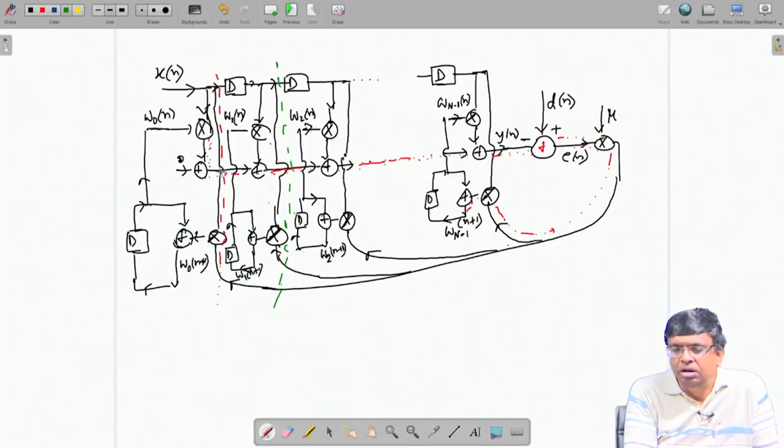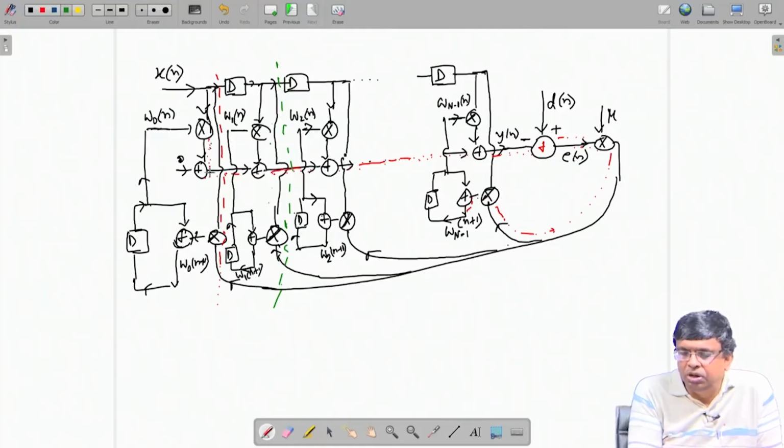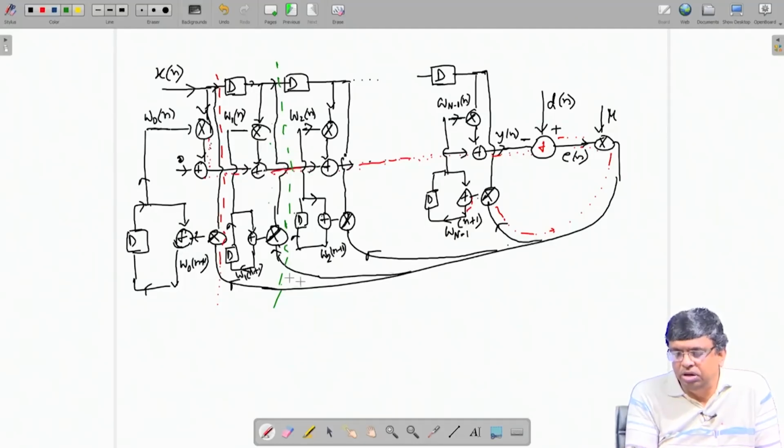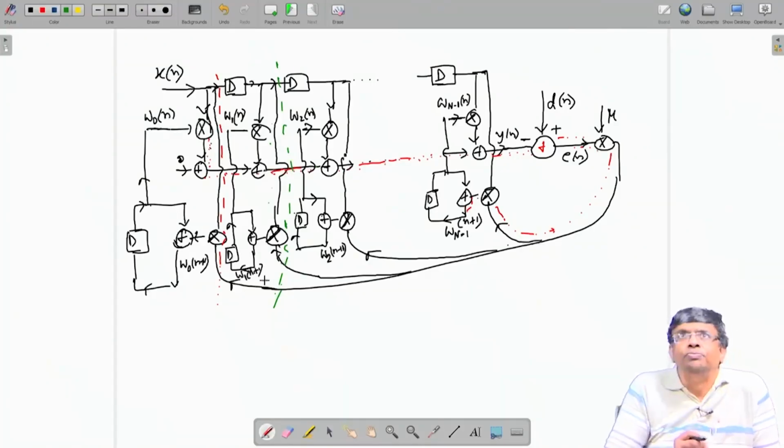That is, I want delays to be between every two adders here, like I did in the case of FIR filters earlier, to bring down the critical path, but the moment I try to put a delay in this direction, I have to have another delay in these edges, they are in the same direction. I have to take out delay from the opposite directions from these edges where it is cutting, but there is no delay in this direction. Okay. That is the reason we cannot do it.